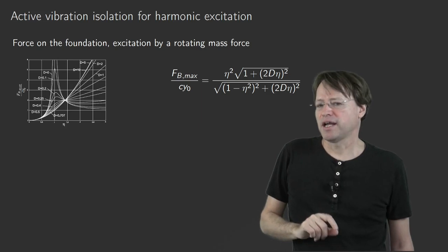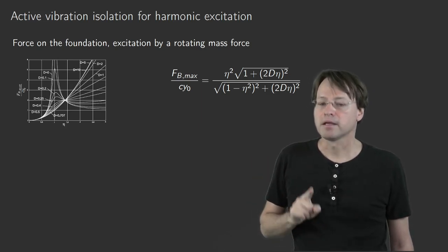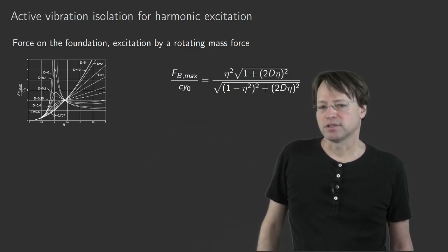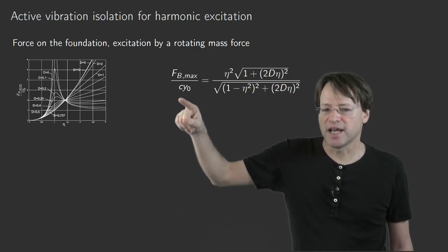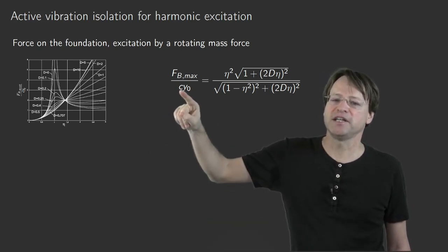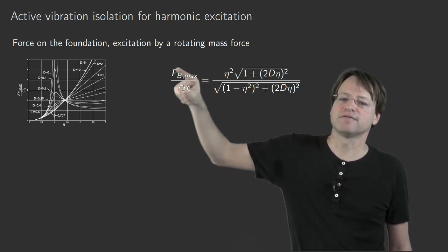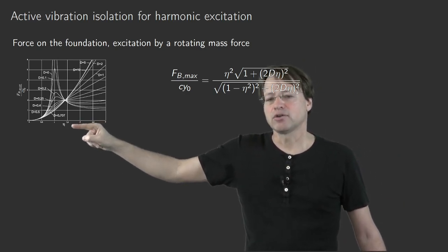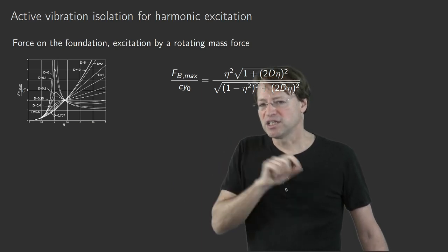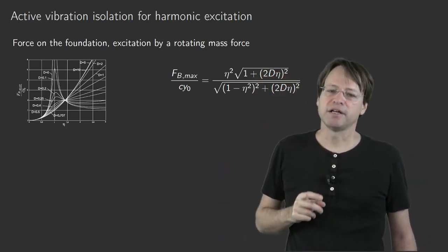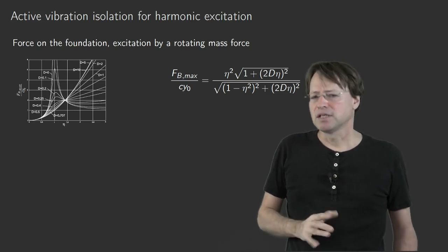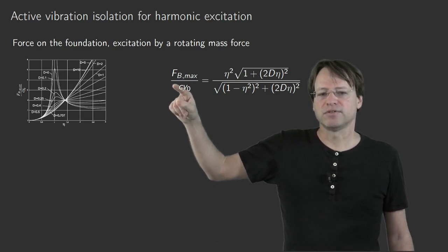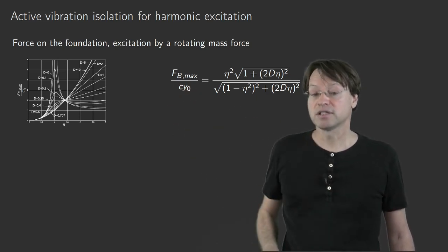However, that interpretation as changing the stiffness is not correct. Look at your ratio. If you change the stiffness here, then what you change is again the denominator of that ratio. So by changing the stiffness, the left-hand side is affected. So basically in that diagram, you study the effect of changing eta. Changing eta can be obtained by changing the natural frequency. As the mass of your machine is usually fixed, that is obtained by changing the stiffness of that connection. However, you change the left-hand side.